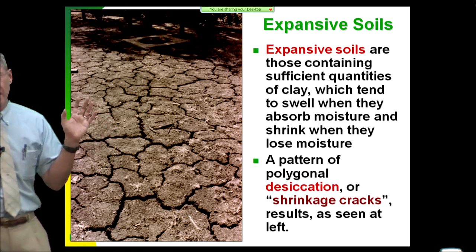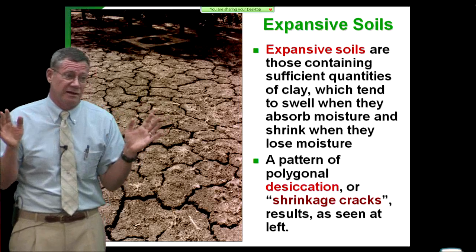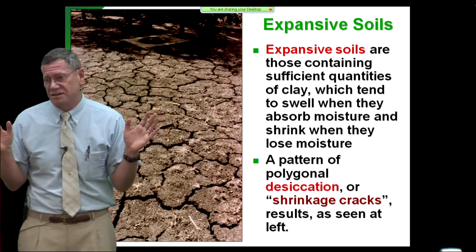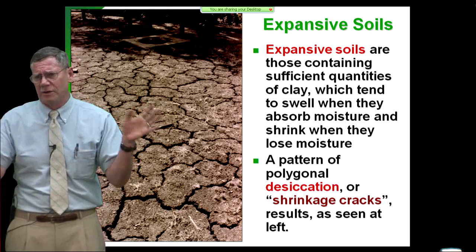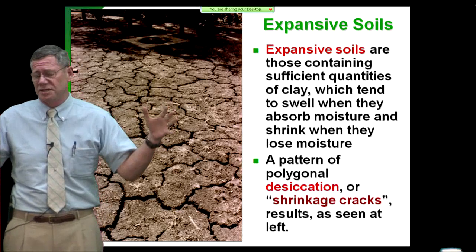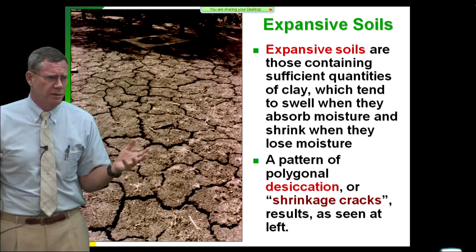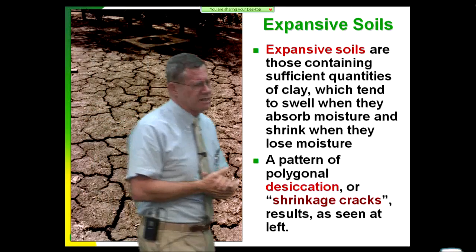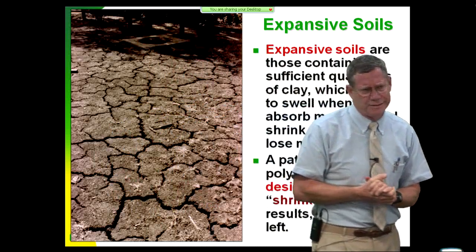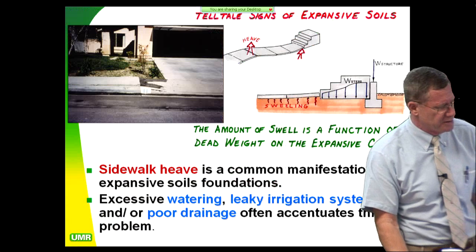Smectites are the really bad news. That's like catching HIV. You get smectites in there, give the job to somebody else. Run. Go practice somewhere else. Smectites can swell up to 300 to 800% of their dry unit weight. They're generally altered tuffs, specifically in the United States, mostly of Cretaceous age. The Bearpaw, Pierre, all those that are so famous.